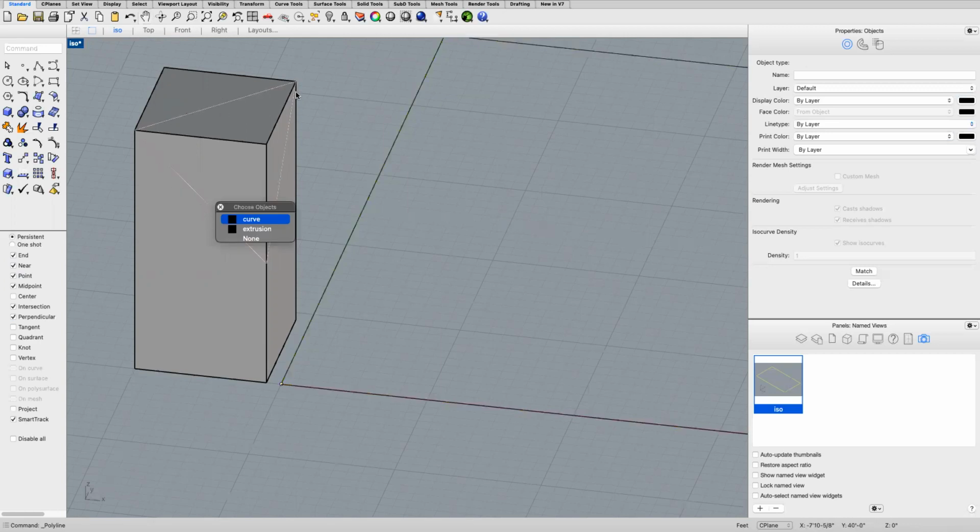That way, when you select on that curve and look in your object properties, right? You always want to have your properties palette up. I'm not worried about layers in this tutorial, but your object properties will tell you what you're dealing with. So now that I have that selected, I can look up here at my object type, and I know it's a closed curve. Typically when somebody comes to me and has problems with their geometry in Rhino, that's the first thing I look at: what geometry are we dealing with?